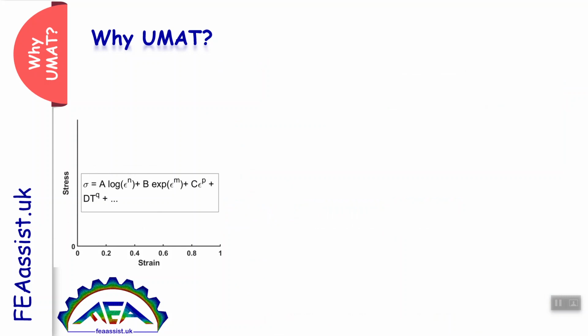But consider you have a new material or a new constitutive equation. The equation between stress and the components is very new, which is not included in Abaqus, and you don't have points. So what can you do? Then you need a place to write this equation or your equations and tell Abaqus to obey this behavior to solve my problem. This is the reason we need UMAT, because our equation is new.